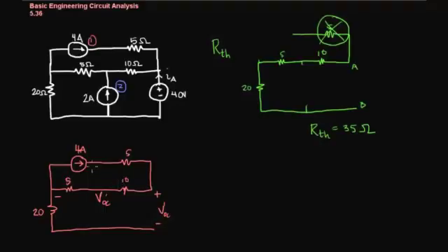So let's make sure that we understand what their polarity is, and by the current source here, you'll find that we have the same polarity with V prime on the open circuit as we do with the voltage across the resistors. Okay, so V prime is going to equal 4 times 10 and 4 times 5. So V prime equals 60 volts.